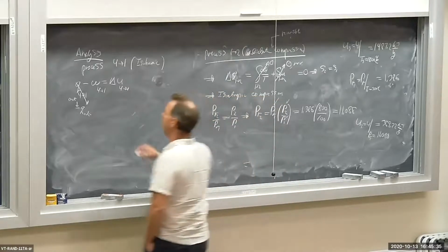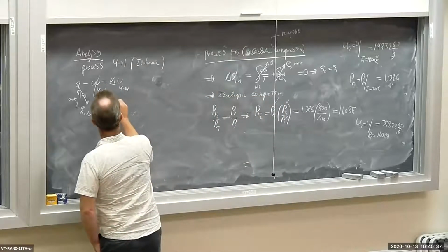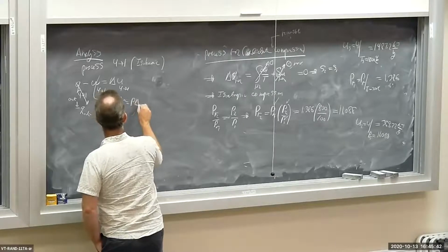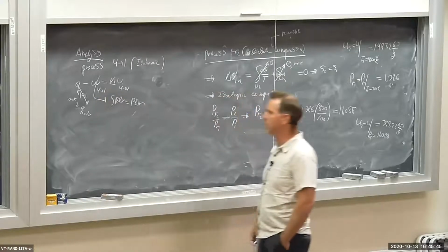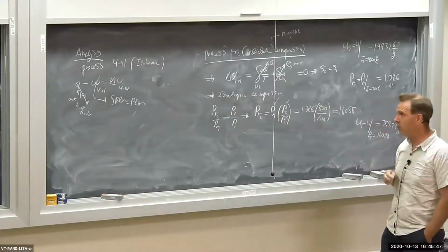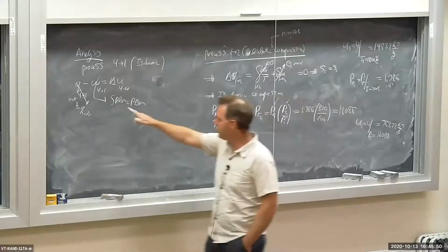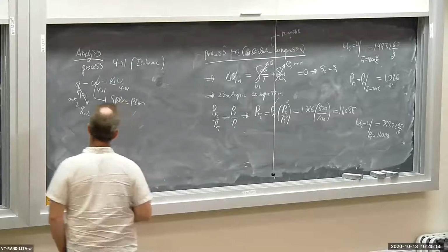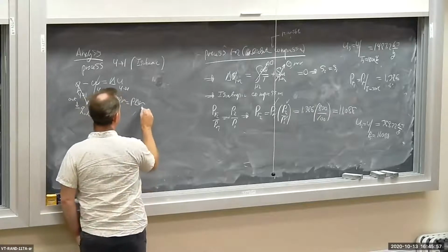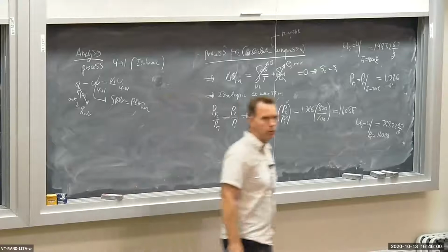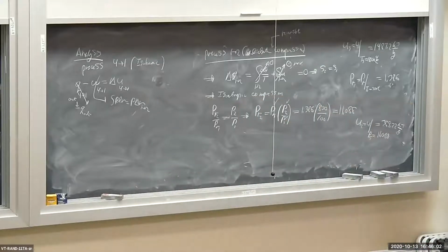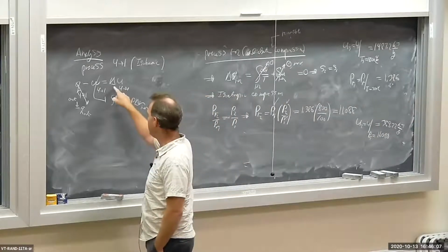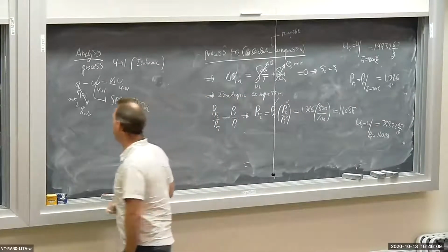So the integral of P dV is equal to pressure times the change in specific volume. That's specific work. It's an isobaric process. I can pull the pressure out of the integral, and I get P delta V. Okay, fine. Now what I'm going to do is take the P dV and put it on the right-hand side of the equation.